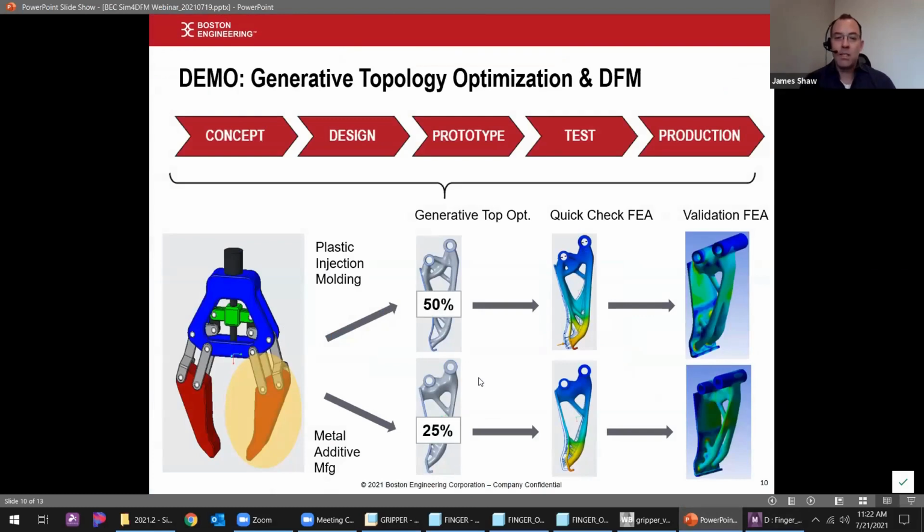What happened was a single designer in a single environment just did two things at once. That was to shave weight, for lack of a better word, or optimize the design as a mechanical engineer might do. I've targeted two different materials. I've targeted two different manufacturing processes because I subscribe to the design for DFM process. And I've successfully used two different kinds of simulation. I used a quick one just to make sure I was getting the deflections I needed. And I used what we would call a validation FEA, where I can get a true factor of safety. I can build in more advanced, nonlinear dynamics, anything you would want at that point. Any of the multi-physics that we talked about earlier is really needed if we're going to be using DFM up front.